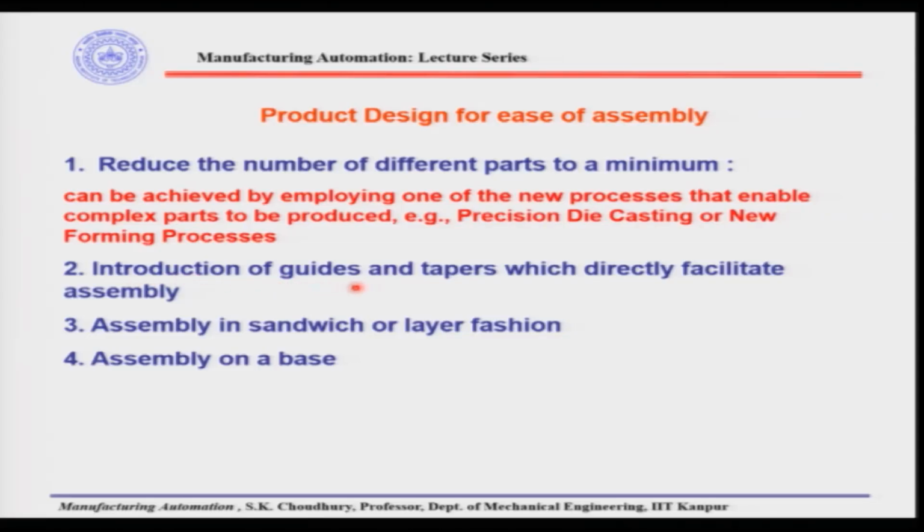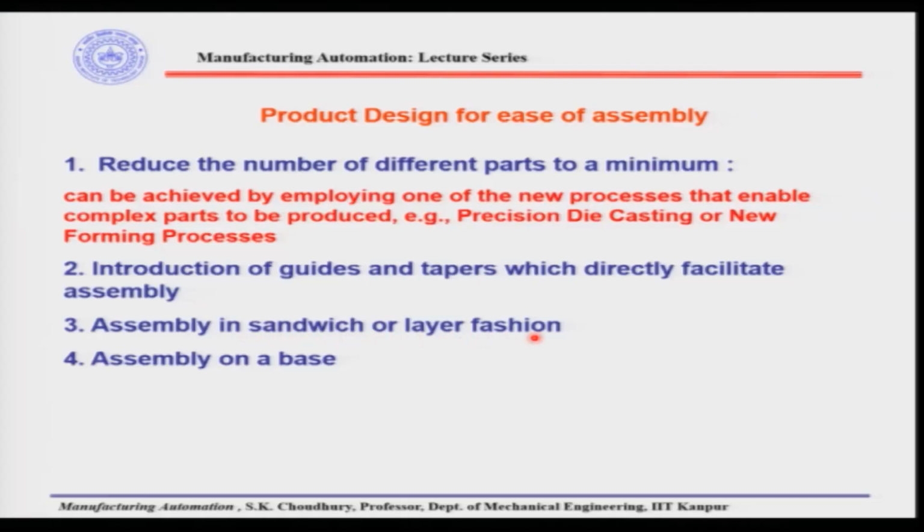Second point is the introduction of guides and tapers which directly facilitate assembly. These examples we will see later, how the implementation of a taper or a chamfer could facilitate the assembly. Third is assembly in sandwich or layer fashion, in the sense that when the assembly is made, it should preferably be made on a base plate, and then parts should be stacked one on top of another, and access to the sub-assembly or the assembly should be from one direction as far as possible. That is what we mean by assembly in the sandwich or layer fashion. We will see the example. Assembly on a base, as I said.